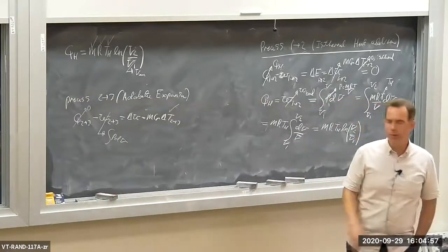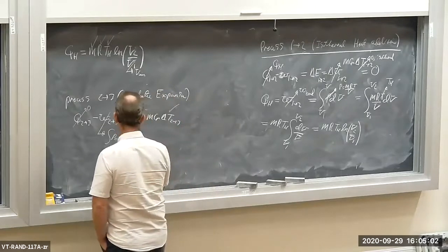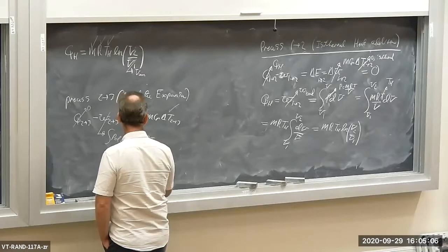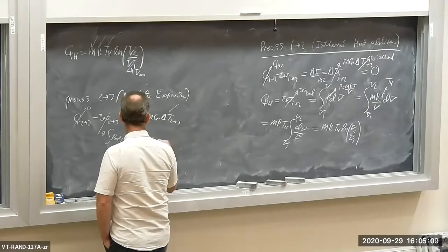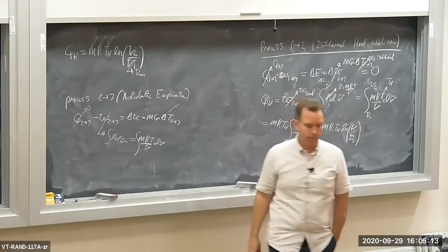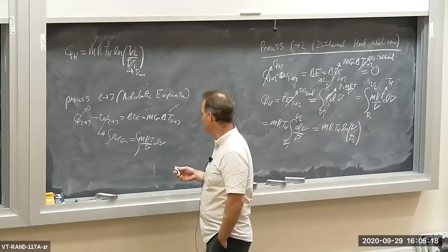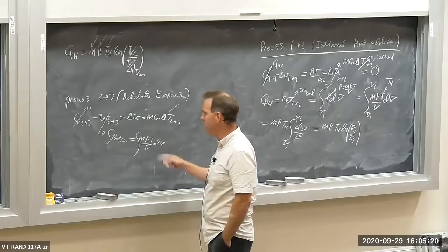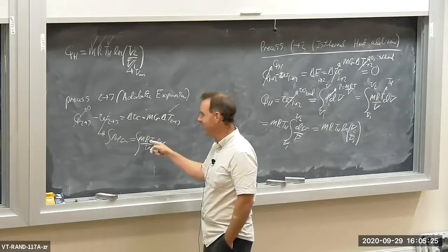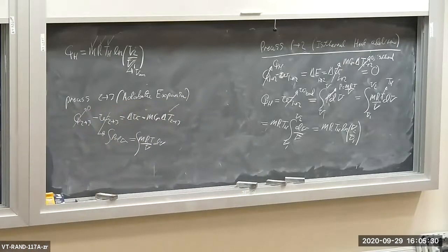And of course, pressure is a function of, according to the ideal gas law, a bunch of stuff. I'll have an mRT over V dV from V2 to V3. Now, I'm kind of stuck at this point. I'm trying to get a volume, V3, but volume's buried inside of this integral and temperature is not constant. 2 to 3 is not an isothermal process.